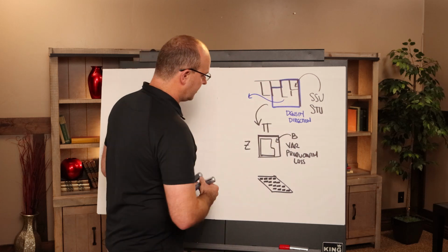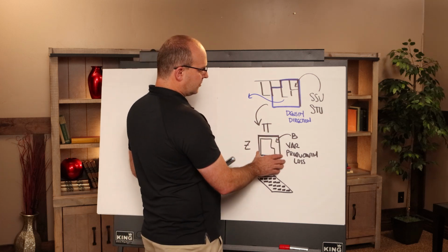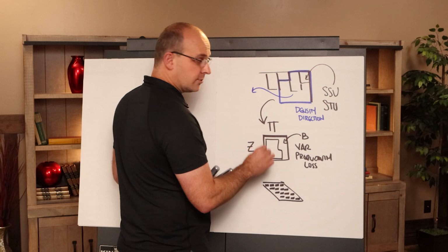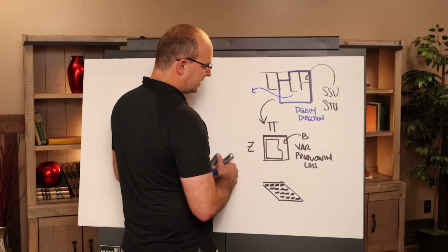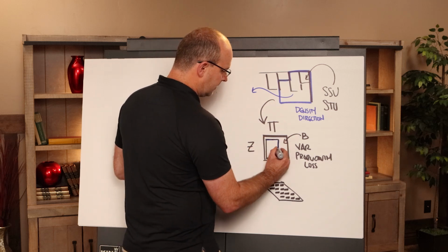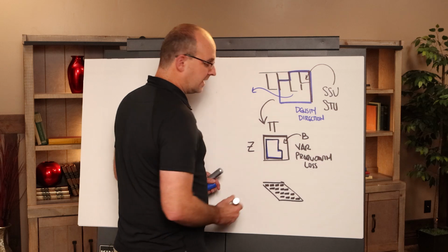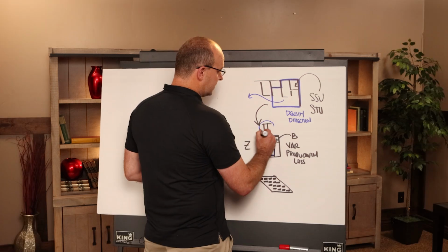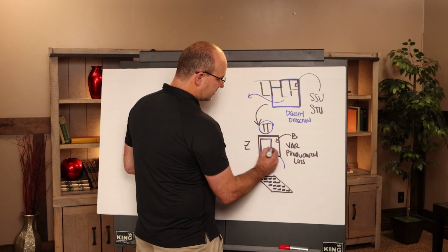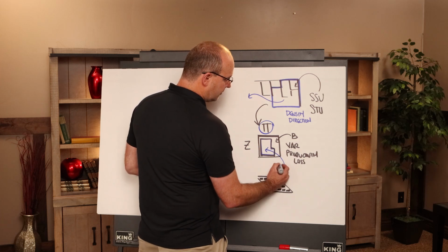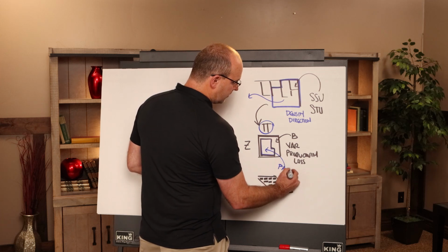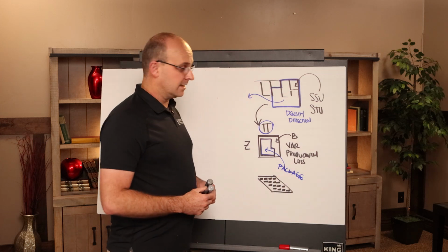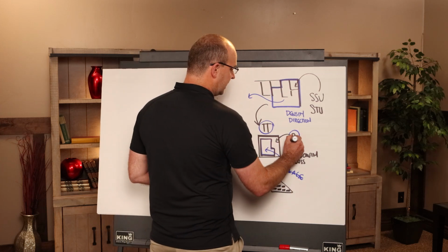Inside the actual wagon itself, we need to know that the crews can fit within this takt time, that they're packaged and leveled appropriately so that they can flow. You'll identify your takt time, how to package the work with the crew inside of it to get done what they need to get done, and how much buffer they actually need.